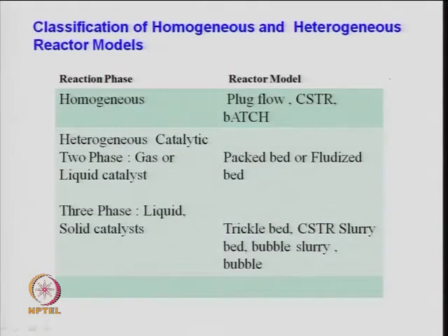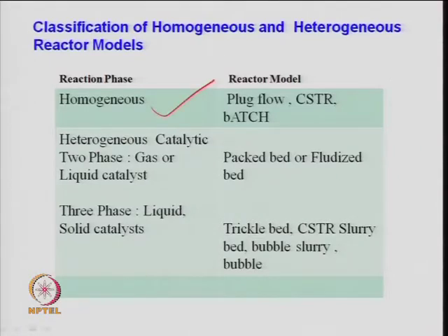In general, if you look at a broader classification for a process, we talk about a catalytic reaction based on homogeneous catalysis and heterogeneous catalysis. So, homogeneous catalysis, when I say so, of course, nowadays it is a new trend that homogeneous catalysts are preferred, because the mass transfer limitation or diffusion limitations are minimum in the case of homogeneous catalyst. So, that is why they are preferred, but as I said, separation of a catalyst is difficult.